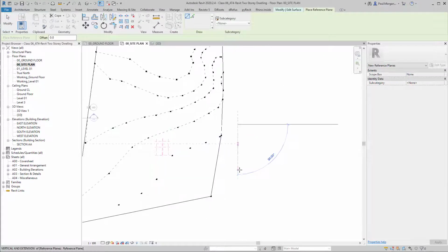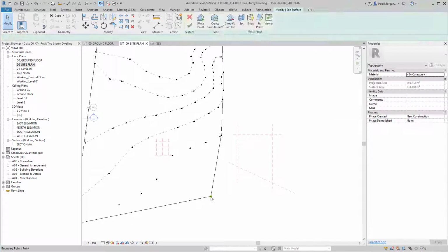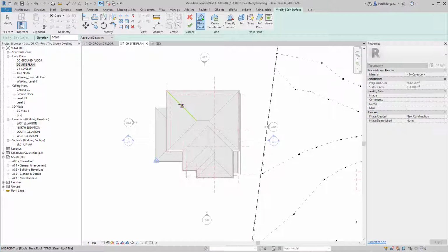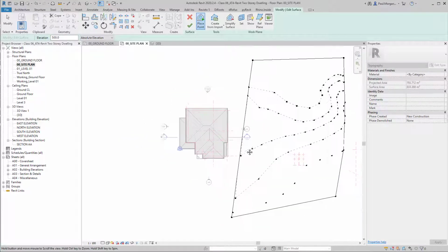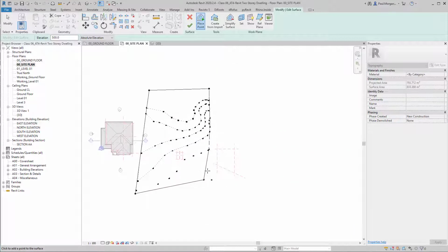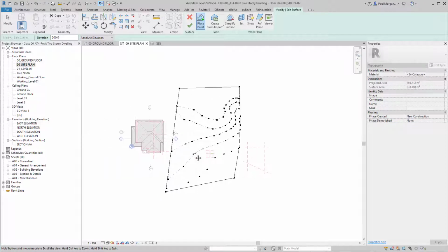You'll see here, if I've got a dead straight site or something, even if it's on an angle like that, these points will snap over those intersections. It's really the one way that I can snap to certain points in geometry, or certain places in space. It will pick up on some geometry of the house, but usually you're not snapping topography to an architectural object or to a building. It's usually to land elements.